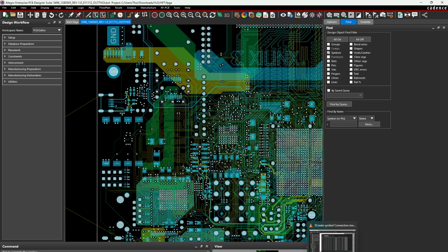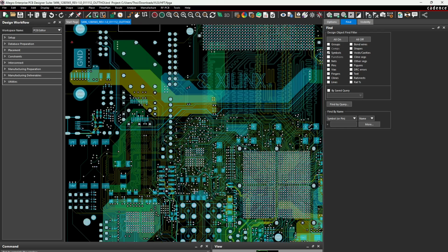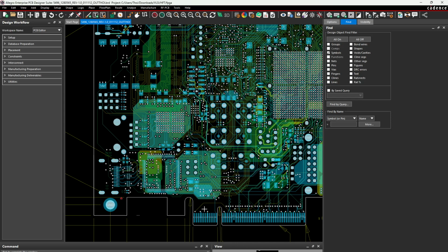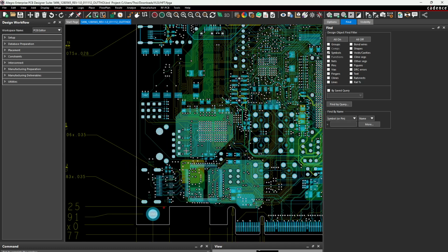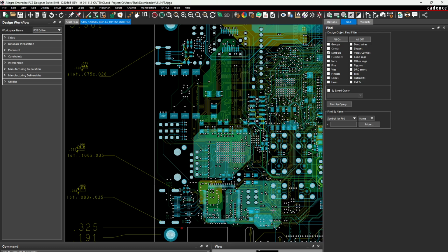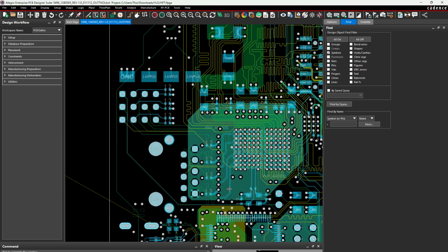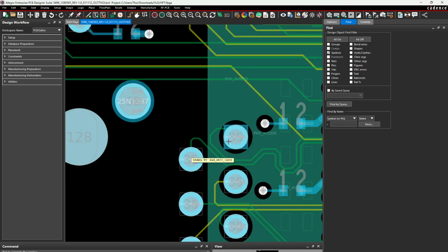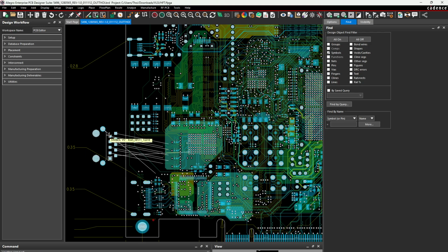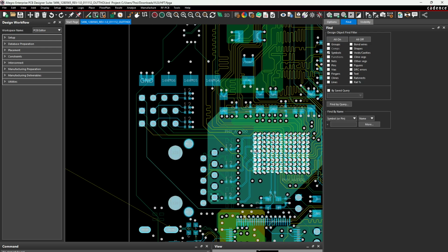If you want to reuse them, or if you have another design, for example, right here I have the Xilinx KC705 FPGA board downloaded from the Xilinx website. I'll make another video for that, specifically related to the Ethernet and all. But nonetheless, I can extract and use the footprint and all from here. So from the layout, I will definitely get the pads, pins, and the footprint. By footprint, I mean, this is the Ethernet port RJ45. So I'm going to get the footprint, or even the IC, whatever it is.